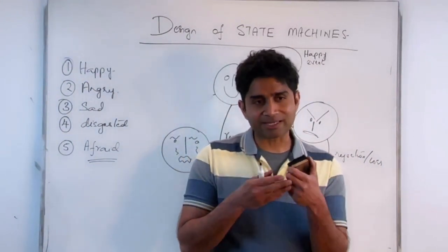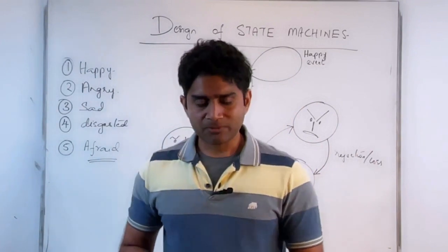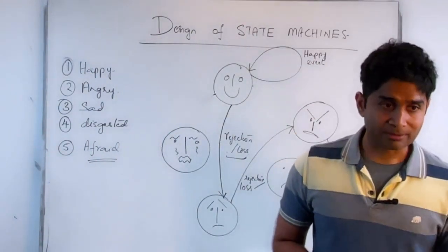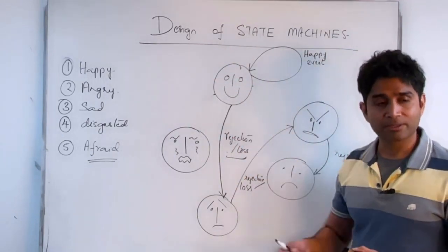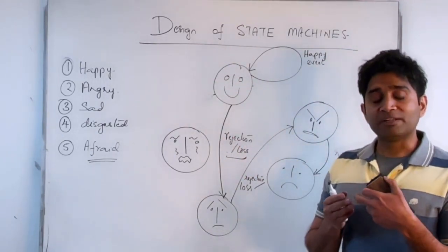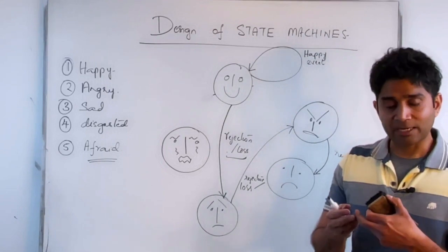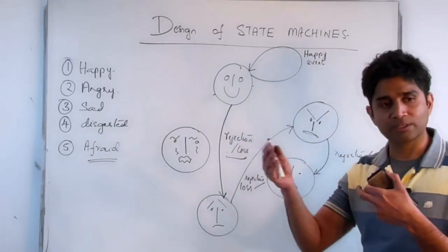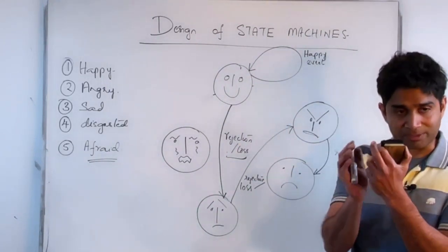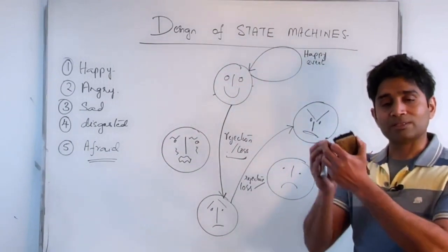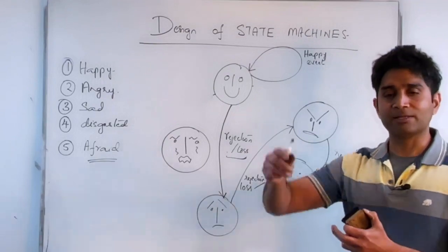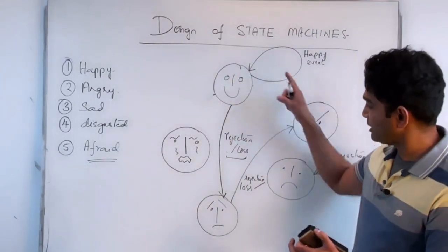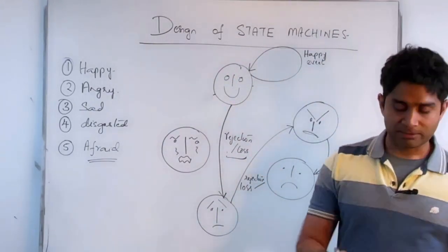So when I'm trying to decide how the state transitions occur, I would go to each state, look at the different events occurring on that state, and draw the corresponding transitions from that state. Once I'm done with a particular state, I would move on to the next state, repeating the same exercise and eventually going through each of my states to complete my state diagram.